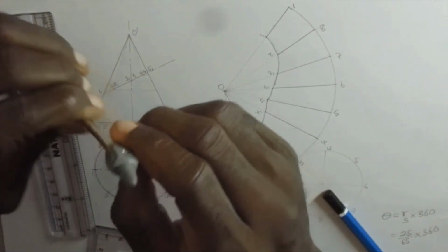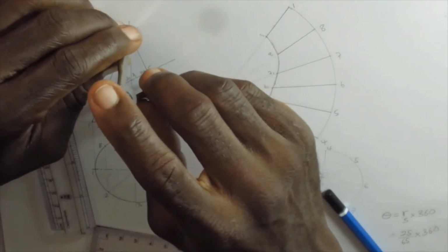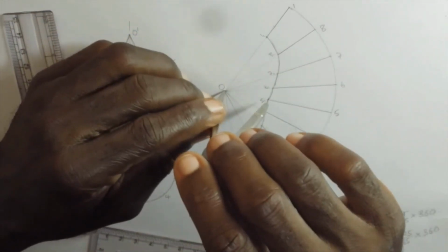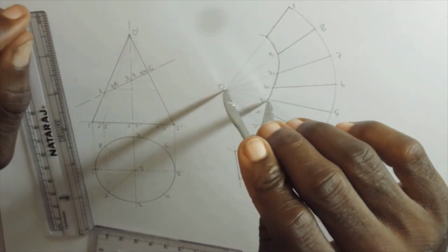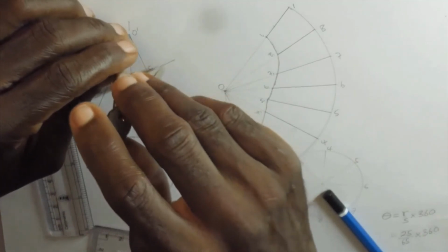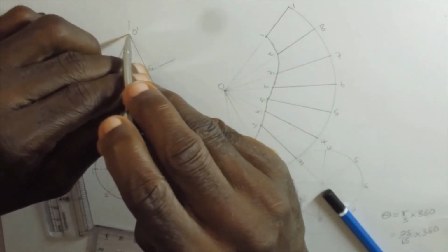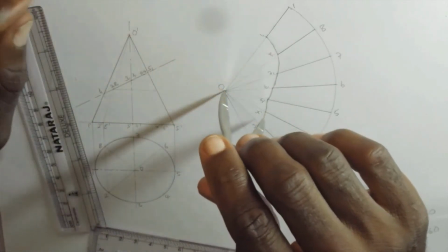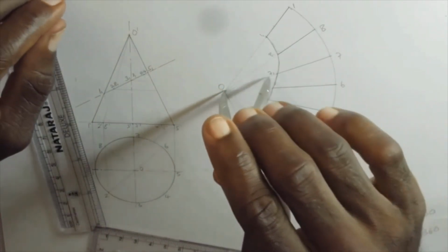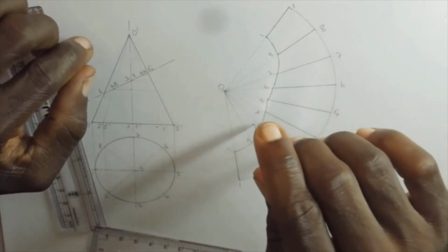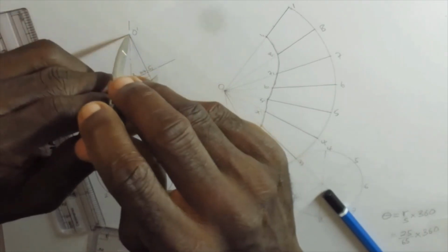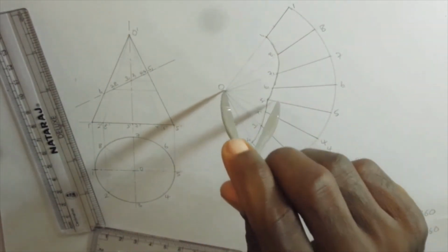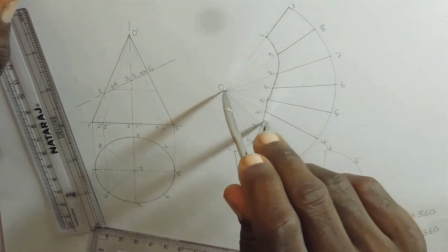All right, so you draw horizontal lines from each of those points to the slanted edge. Then with the divider, we pick those points. So from the apex to, let's say, the point 5 subscript 1, you pick that. Then from your developed cone O, you mark a point on 5. You pick that one for 6 and 4. So from O, you mark the 4 and then 6. You note those points. Then you pick that one for O prime to the next one, which is 7, 3. All right, so when you come 7, then 3, you mark that point.